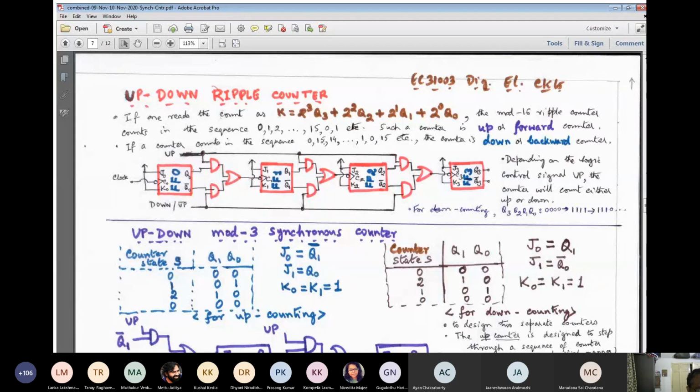After that, you can verify that only this one will be having a transition, not the other ones. Okay. Why also you can tell me that if now it will have a transition, so it will go from 1 to 0, but then Q bar will have 0 to 1. Now that is a rising transition. A rising transition cannot affect a flip-flop with the negative edge trigger, right? So FF1 will remain unchanged, FF2 remain unchanged. So that means from 1111 it will go to 1110.